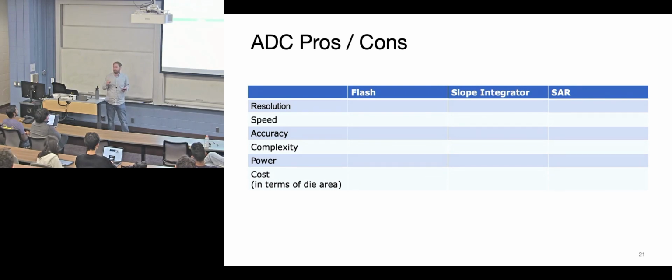Yeah, bad comparators. So if we think about process variation on your chip, if those resistors were not made exactly the same size, then you're going to have unknown voltage differences between those nodes. And so how does that happen?